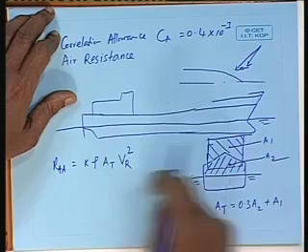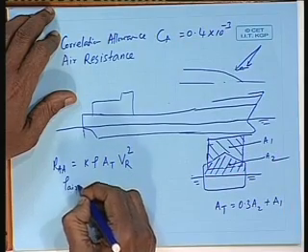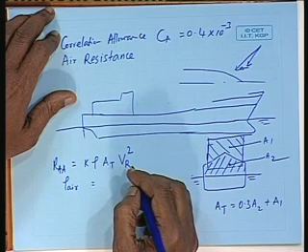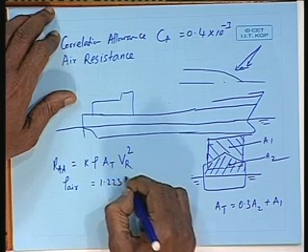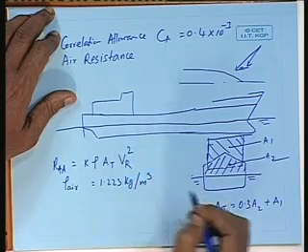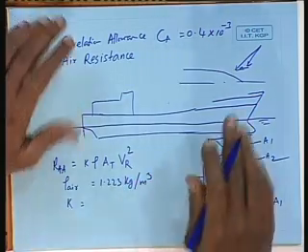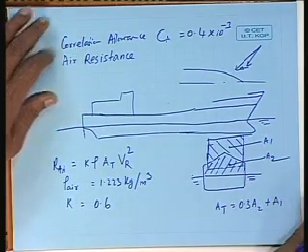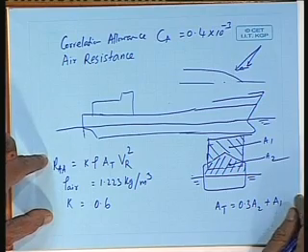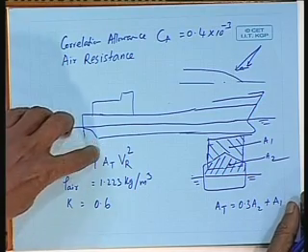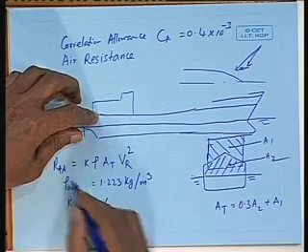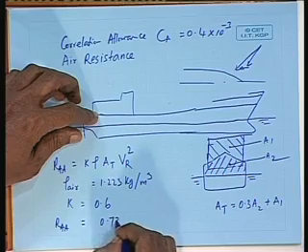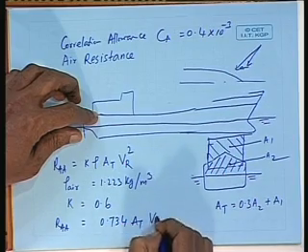A_T is calculated like this, rho is the air density equal to, how much is the rho? 1.223 kg per cubic meter, and K is a constant equivalent to a drag coefficient, which is given as 0.6. So, the total air resistance is given as 0.6 rho A_T V_R squared, which, if you take rho of air as this, then R_AA can be given as 0.734 A_T V_R squared.